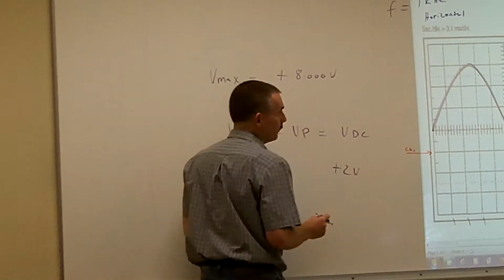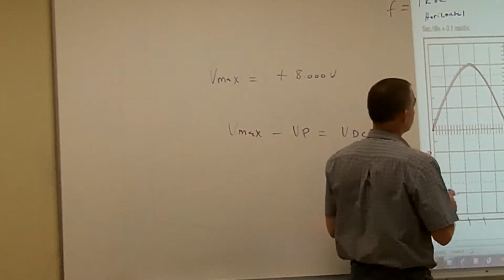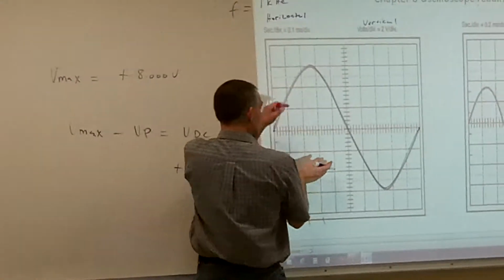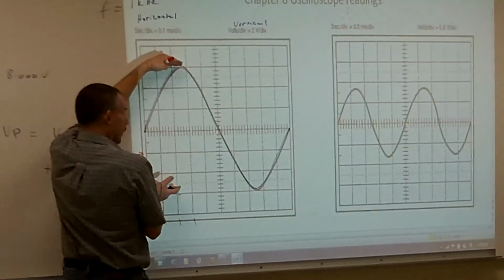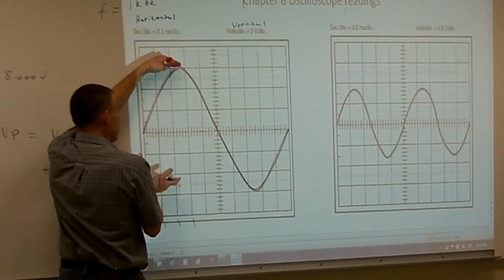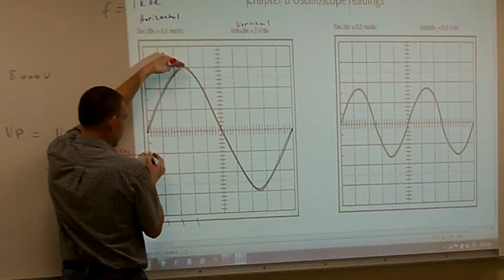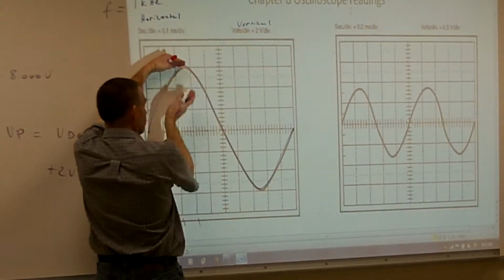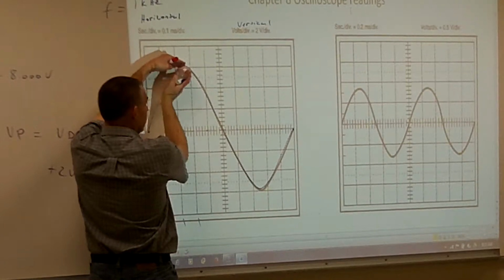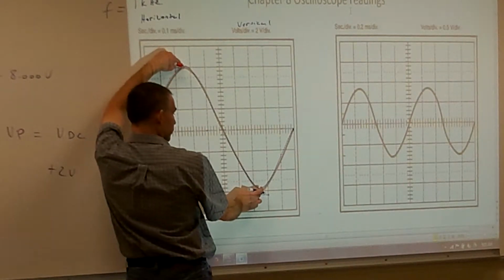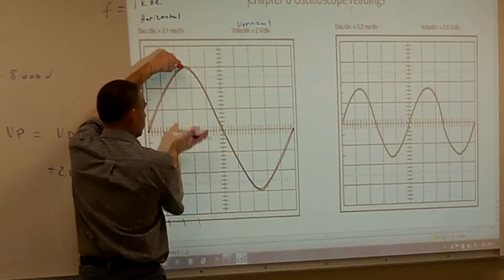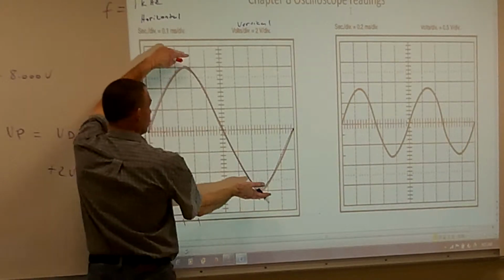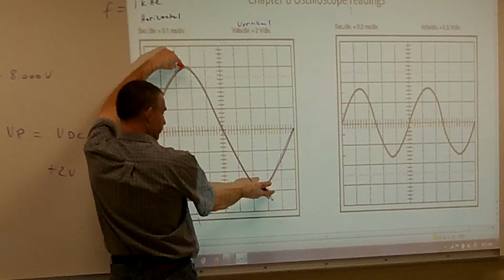Okay? So a lot of times you need to know where that DC reference is. So first of all, just calculate out what your Vmax is. You're going to know where your zero is; your oscilloscope is going to tell you where your zero is. Calculate out what your Vmin and your Vmax are. Calculate out what your peak to peak is, because you can't really calculate your peak since you don't know where your DC reference is.